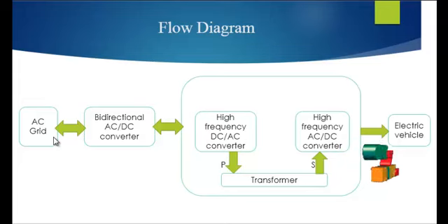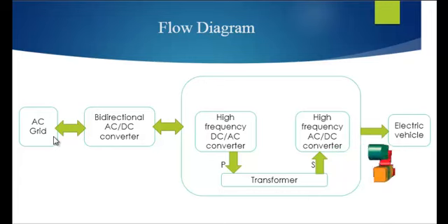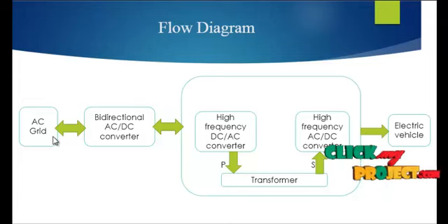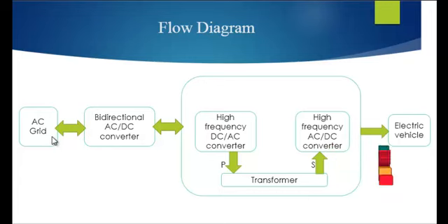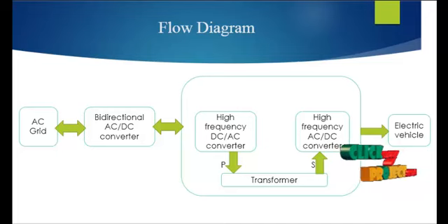The AC converters with approximately sinusoidal input currents and bidirectional power flow can be realized by coupling a pulse width modulation rectifier and a pulse inverter to a DC link. The DC link is used as an energy storage element common to both stages, with capacitors providing the DC link voltage. The DC link current is primarily determined by the pulse rectification mode of the sinusoidal AC line current drawn in phase, and anti-phase energy feedback corresponds to the AC voltage line.